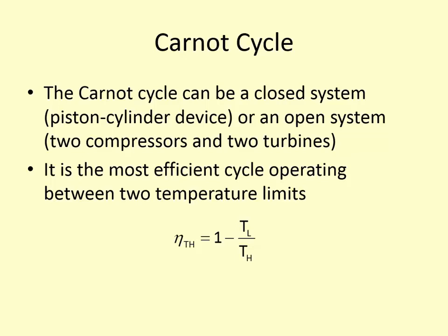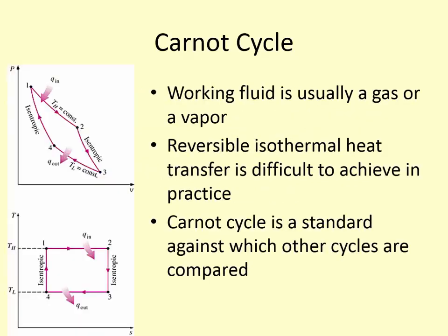And although the Carnot cycle doesn't fit our needs for a lot of the processes that we want to undergo in real life, it does, again, provide that upper boundary. So we can say, okay, what's the best we could do if it were a Carnot cycle? Oh, 26%? Okay, so maybe this 24% efficient engine that I've designed isn't so bad, right? So it gives us the upper limits to what we can actually do, even if we can't ever achieve it.